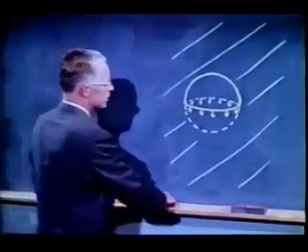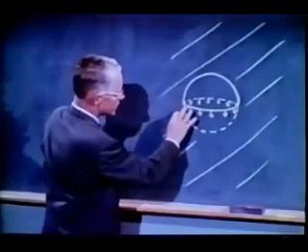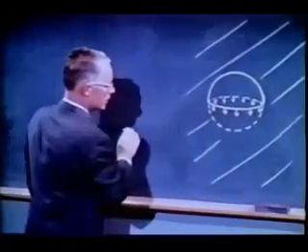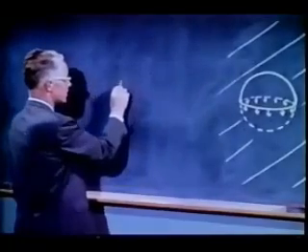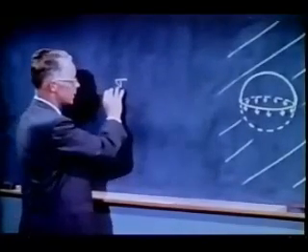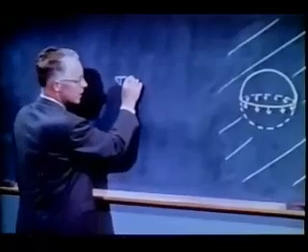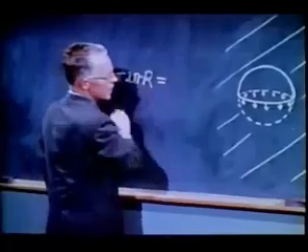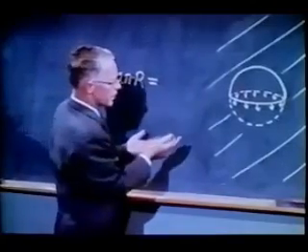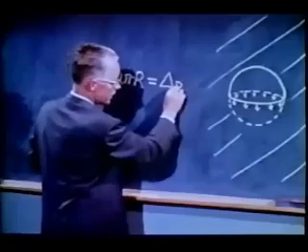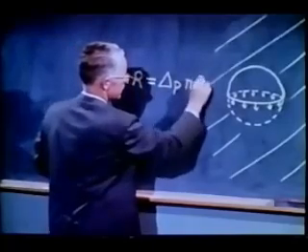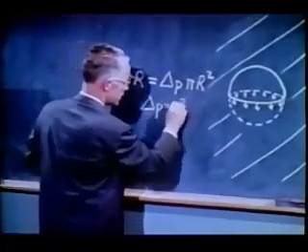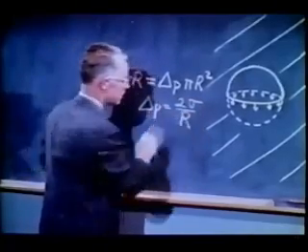We can calculate this higher pressure. Consider the upper half of a gas bubble immersed in a liquid. Surface tension will pull down all around the equator with a total force equaling the surface tension expressed as force per unit length times the length of the circumference. That must be balanced by an upward force, the pressure difference, times the area at the equator. This simplifies to the pressure difference equaling twice the surface tension divided by the radius of the bubble.